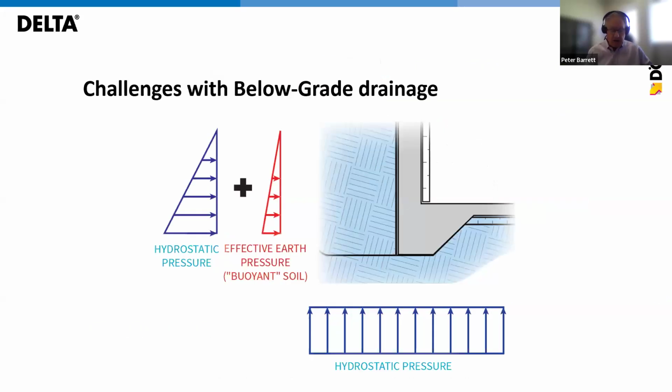What are some of the challenges down there? Well, it's important to have a reliable drainage system in place to prevent water damage in any construction project. If the waterproofing system isn't done correctly, hydrostatic pressure can build up, and even the smallest foundation crack can become an entry point because it has our 3 features: water, pressure, and a hole.